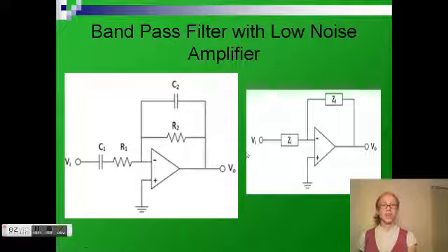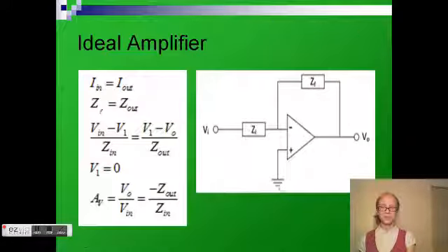So, if we take our capacitor and our resistor and change them into their equivalent impedances, then we can combine them in parallel and combine them in series and represent them as this circuit. Our op-amp with our differential input pair and our single output. Now, taking this squished version, we can recognize it as an ideal op-amp. For an ideal op-amp, there is infinite gain, which means that the input voltages are exactly the same.